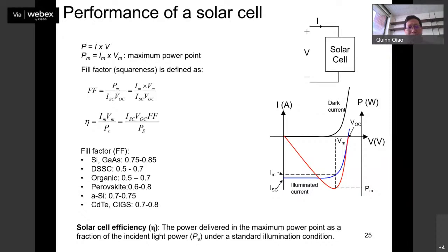Yeah. So professor, the fill factor you have described here is only for lab-scale areas like 0.2 mm square or so? See again, the fill factor you have shown here for the DSSC, perovskite solar cell and organic solar cell is what they typically consider a good fill factor. If you make very poor devices, you can have 0.1, 0.2. You know what I mean? Commonly, people report a good one, right? There are always bad devices where you can get 0.1, 0.4, 0.3. All these are possible. Yes, sir, it is always there.